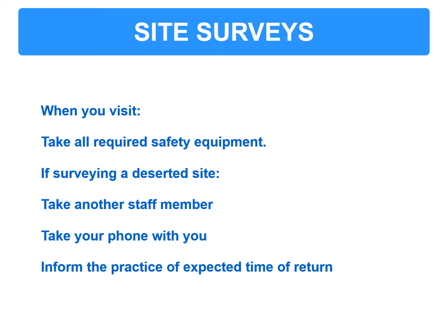But from a safety point of view, surveying a site alone also carries a risk, particularly if it involves derelict or very old buildings or soft ground, for example, or if there's any other risks associated with being out there on your own. So take another staff member. If not, take your phone with you and inform the practice of your expected time of return, just to be safe.